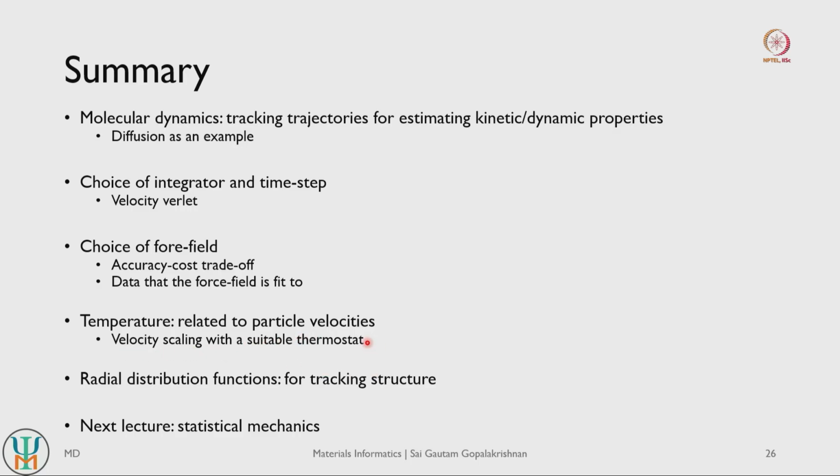And if you want to control the temperature, you use a suitable thermostat, right, and you do velocity scaling. You scale your velocities using this thermostat so that your temperature is fixed during a simulation. And radial distribution functions are very useful. These can be readily calculated over the course of your molecular dynamics simulation, and these are useful for tracking structure, right, and examining structural evolutions in your system.